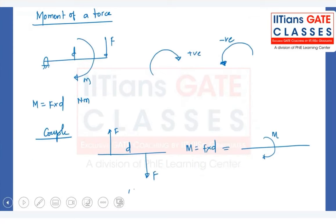Moment of a force. A moment will be generated whenever we apply a force at a certain distance. Let's take an example. We have a certain force applied at a certain distance from, let's say, a fixed point or hinged point. Because of this, the force will create some moment, and the value of the moment will be the force into the distance. Moment is nothing but a turning effect or rotational effect created by a force applied at a certain distance.